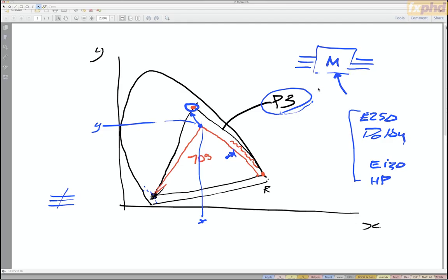But when you do so, all you're doing is building the correct colorimetric transform into the data path to take the 709 numbers. So if you take any of those displays and you set the user interface to 709 color space, what you're doing is inserting a matrix that takes 709 colors and produces the correct RGB device values for the display device to produce colors that are correct for 709.